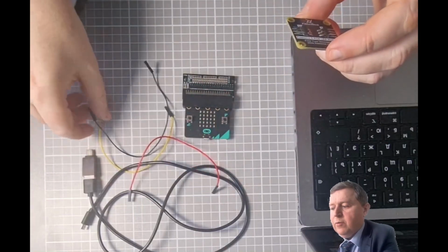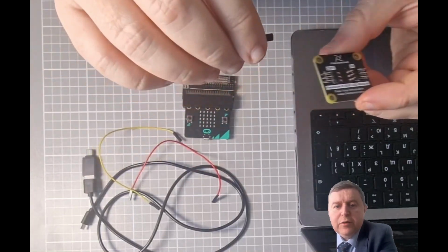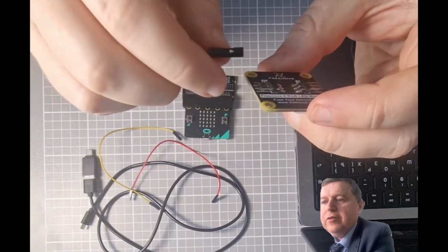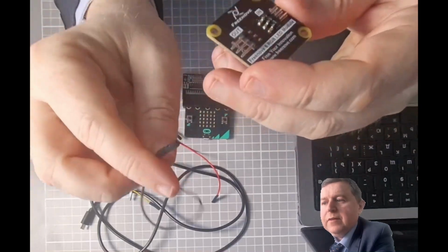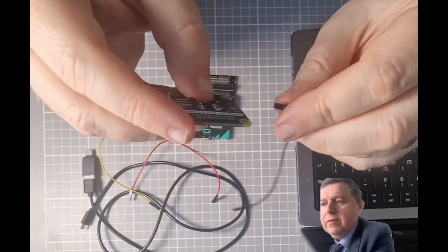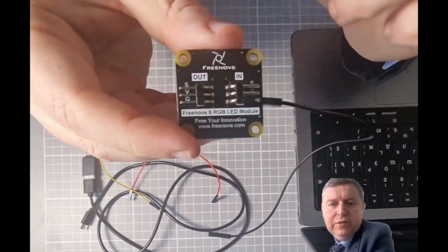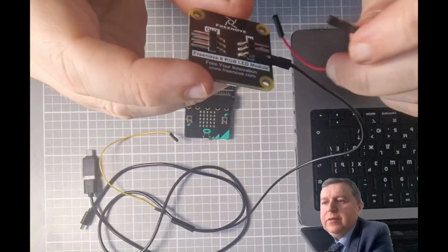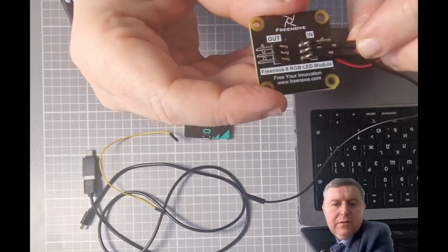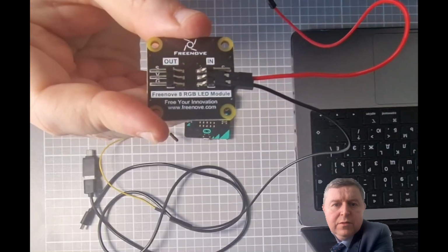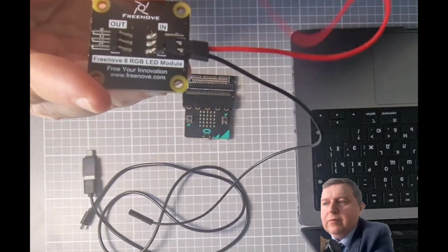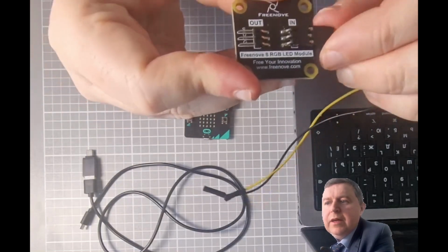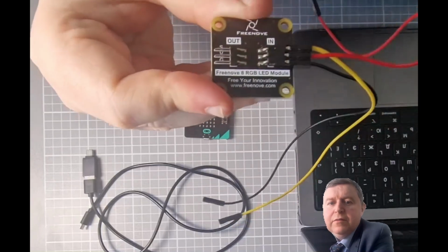So I'm going to put those together on here. Generally it doesn't make a difference what color they are, but we usually use the black one for ground. If I find G on here, you should see there's G, on the bottom there. Then voltage is usually red, which is V on this one, so I just plug it in. And then the last one doesn't make a difference. It's a signal, so it's going to send our signal to our NeoPixel. So we're going to put that in there, and make sure they're all pushed in.